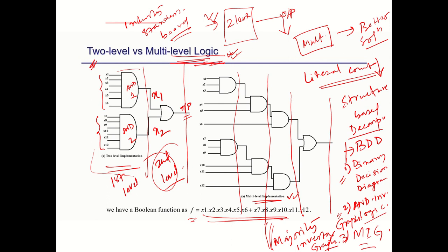So this is all about two level synthesis and multi-level synthesis, but we have not defined them in detail. Is the concept clear, what is two level, what is multi-level? Yes, sir. Okay, in multi-level, different levels will be created and we try to minimize the number of product terms or literals or all those parameters, which are given in our specification as your desired parameters. You need to minimize all those and find the particular net list which gives us the minimized net list for this problem.